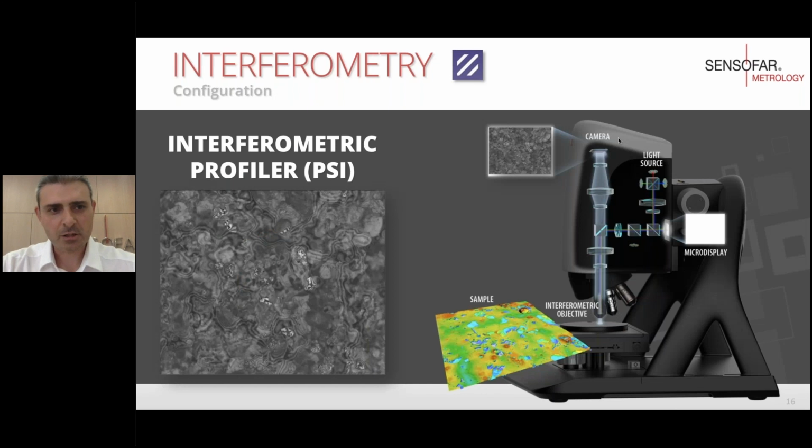So okay, in the Sensofar systems, which was a subject of the previous webinars we did, we have a micro display that displays different patterns on the field of the microscope, and then we have a red, green, and blue light source going through the micro display. The micro display in that case is totally useless for interferometry because we turn on all the pixels, so it behaves like a bright field illumination microscope. And then after that, we have a white light LED placed exactly after the second beam splitter you see here on the screen.